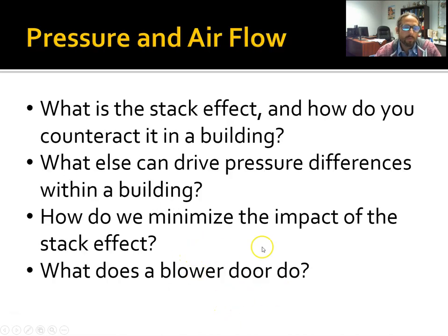Okay, so now hopefully you have a good sense of what the stack effect is and how you can counteract it in a building. Remember, you counteract it by sealing the top and the bottom. And you've learned about other ways that pressure differences can occur within and outside of a building, and then also how we use a blower door and what that does in terms of pressure.